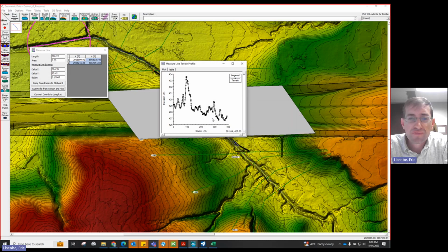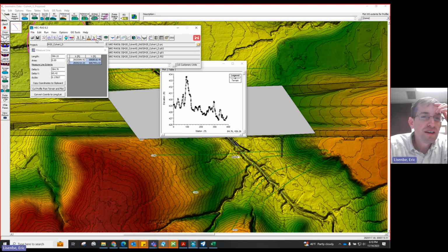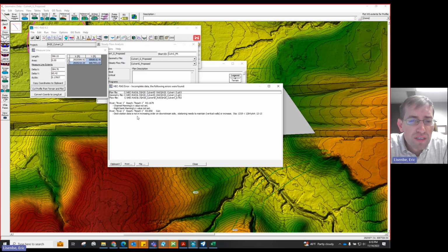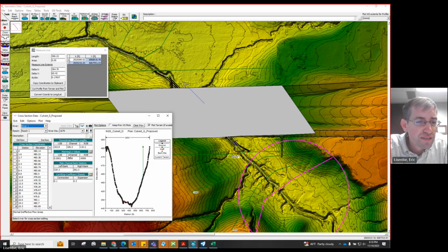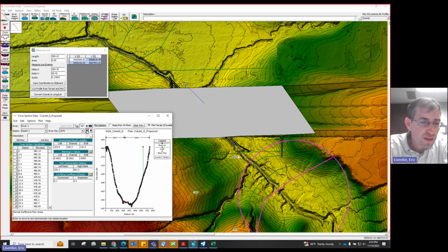Okay, my data. I think that's good. I think I'm okay to run it, and I'll see how it goes. Bridge 1 deck station is not increasing, or so on. Channel Mannings n not set. So river station 1679. Okay, I haven't set all my n values. Looks like I just missed one. So that needs to be 0.07.